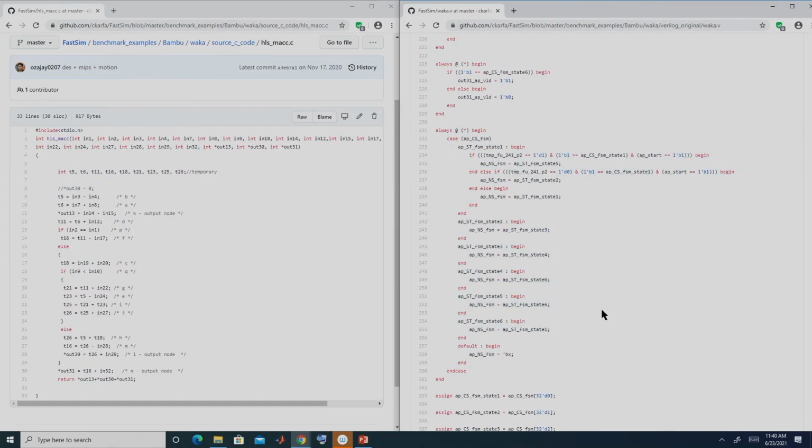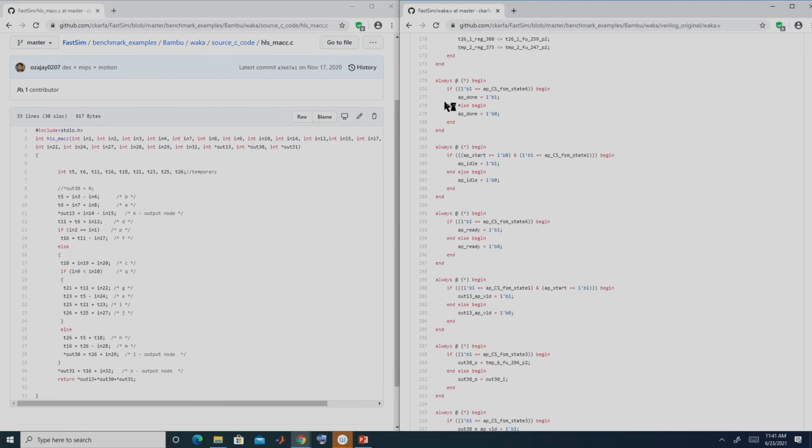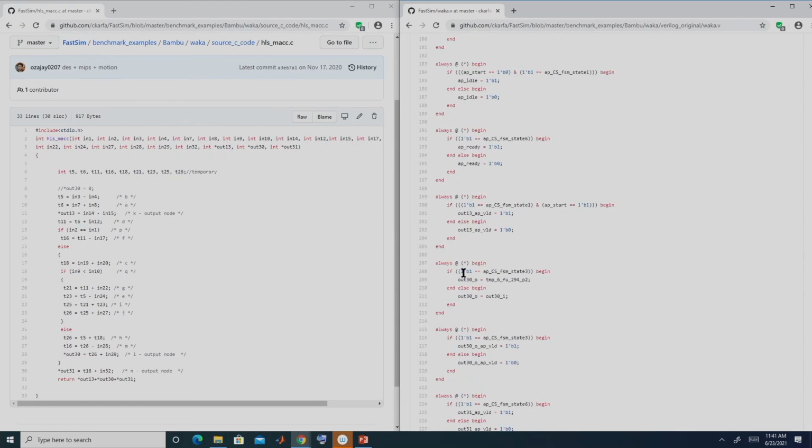So, this is the FSM, the controller FSM, right. You can see here that in state 1, if such condition holds, then I will go to this state, otherwise I will go to this state and so on. In this state I am going to do this. This is my controller FSM, the way I just explained, right. And these are the operations that are actually enabled state-wise. For example, if you see in state 6, I am going to do this signal equal to 1, right. Similarly, in this particular state 3, I am going to do these operations. Here this is basically a register transfer operation.